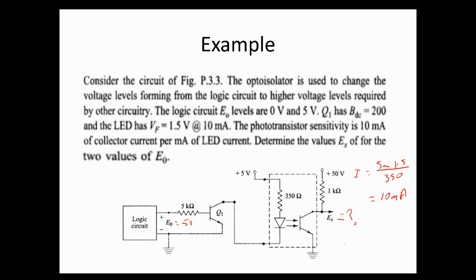You said that regardless of whether it is on or off, there's always 50. Remember, we're measuring with respect to ground, right? When this is on, you measure from this point EX to ground, measuring across the switch. The switch turns on, what's the voltage? 0 volts. Right, so it is when it is off that you get the 50 volts there, right?